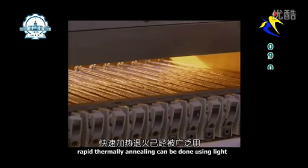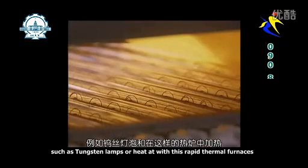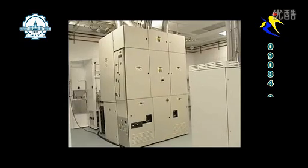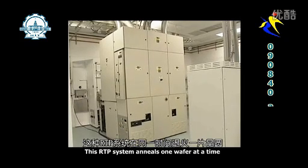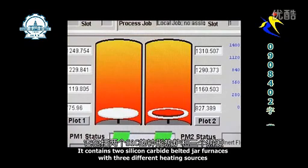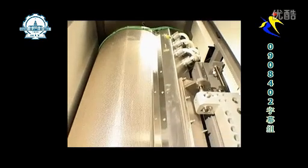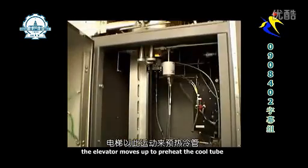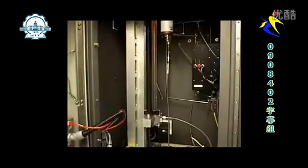Rapid thermal annealing can be done using light, such as tungsten lamps, or heat, as with this rapid thermal furnace. This RTP system anneals one wafer at a time. It contains 2 silicon carbide bell jar furnaces with 3 different heating zones. From underneath the furnace, the elevator moves up to preheat the quartz tube.